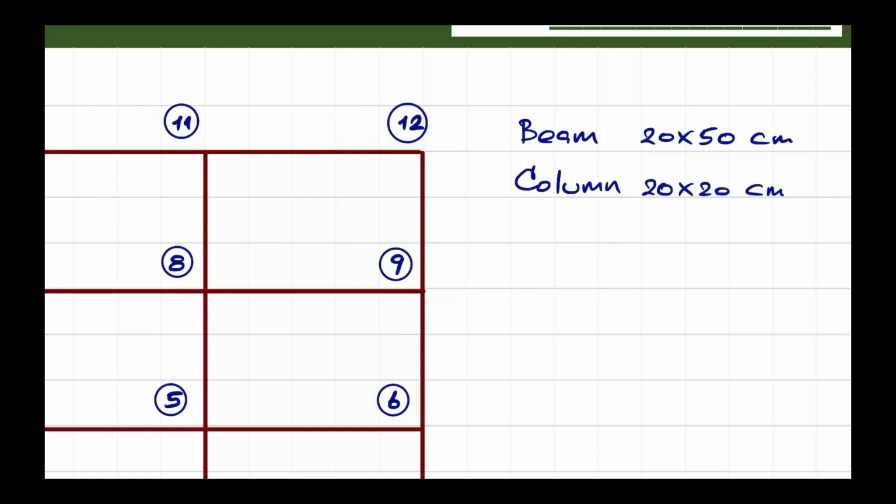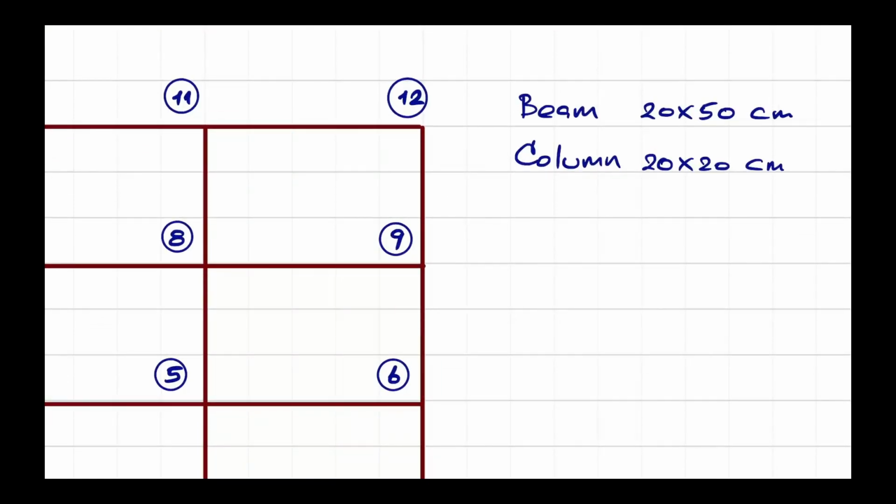Your job is not done there, because your dimension might not match the assumed dimension, so you can rerun your structural analysis by putting in the real dimensions from your design, right? Analyze again, and then you'll get the new distribution, which should be quite close to the analysis from the assumed dimensions, because if you have some experience, you will put quite sensible dimensions in your analysis. So the ratio between the EI or the EA will be quite realistic, from experience.